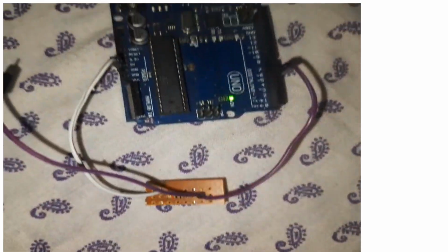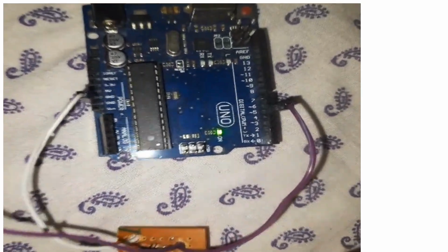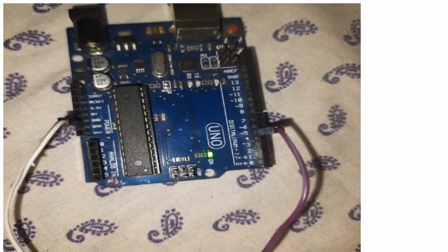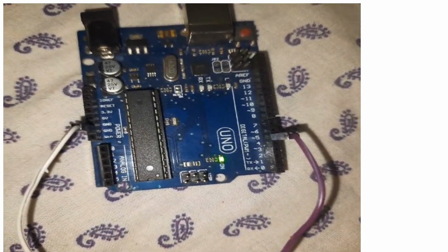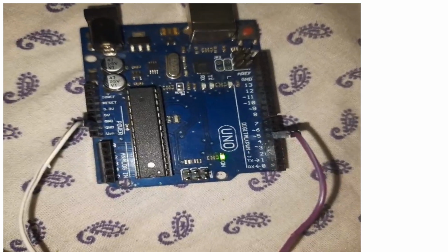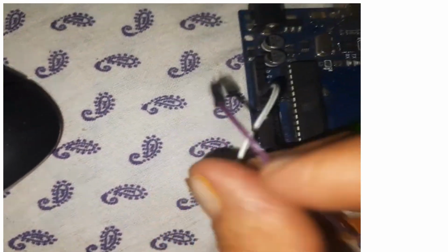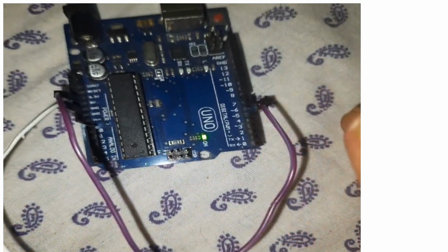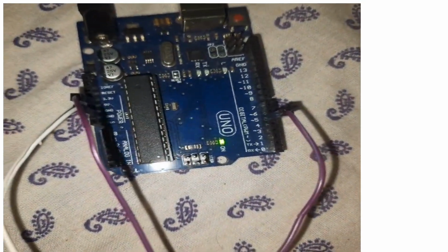So the voltage going to pin number 5 is logic low, and my program reads pin number 5 as logic low. The moment I insert the third fly lead into plus 5 volt socket, the voltage going to pin number 5 is logic high.